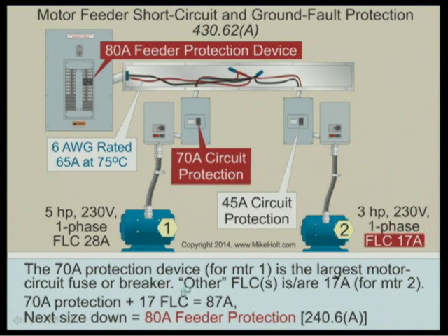Where's the phrase "not greater than" in here? Okay. So it's not greater than 70 plus 17, and if it doesn't land on a standard size, it would be the next size down. So not greater than 87. You can't put a 90 because that's greater than 87, so you have no choice but to put an 80 amp device here. Just so you have an idea, I'm not going to go any further. Let me stop right now.